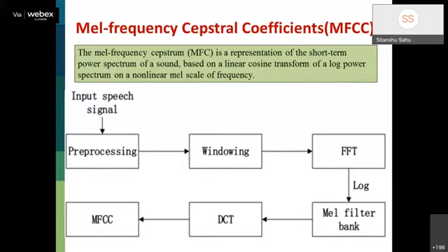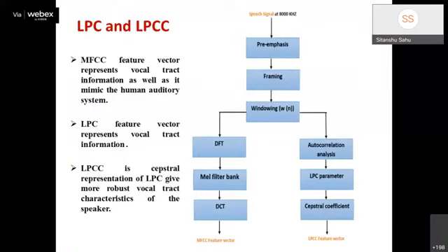So okay, so this captures the MFCC features. Similarly, in the LPC and LPCC, it will be the same procedure. After windowing the speech signal, we have autocorrelation analysis, then we do the modeling like the linear prediction coding. The linear prediction coefficients will be taken in the spectral domain, which leads to LPCC features.